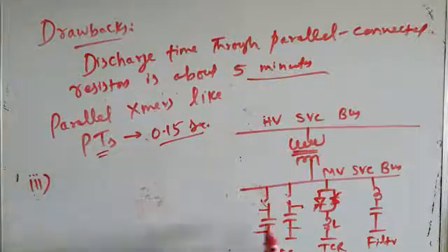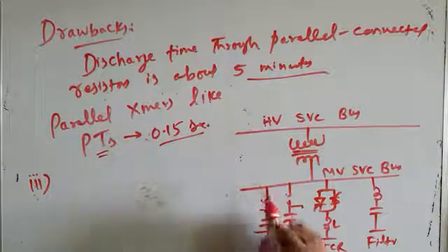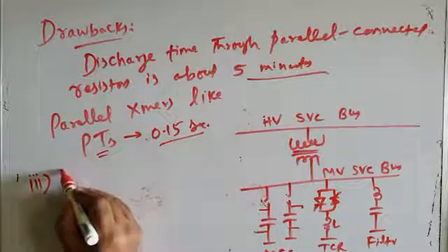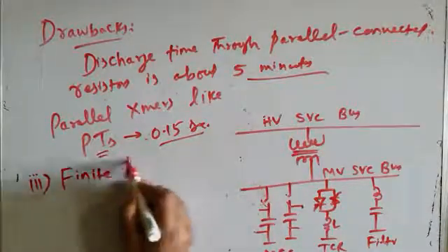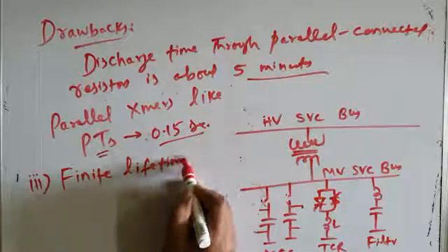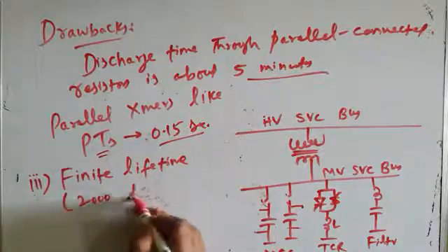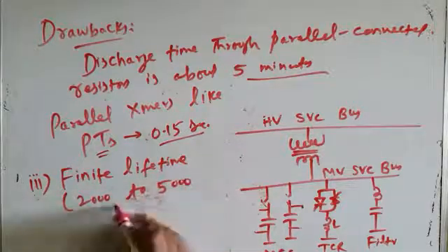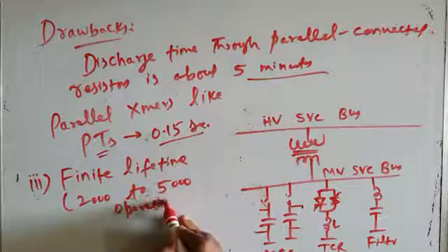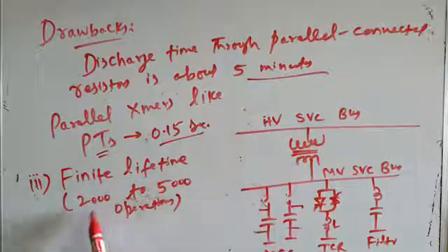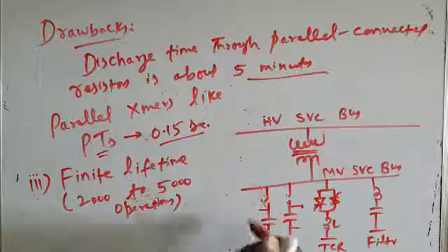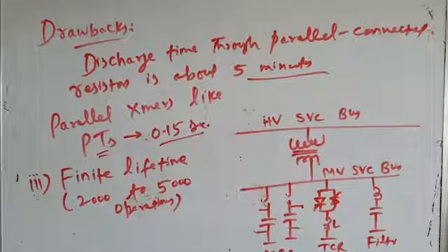The third drawback is that these mechanically switched capacitors use mechanical switches, and mechanical switches have a finite lifetime, generally 2000 to 5000 switching operations. After that you have to replace them, because turning on and off always involves wear and tear.